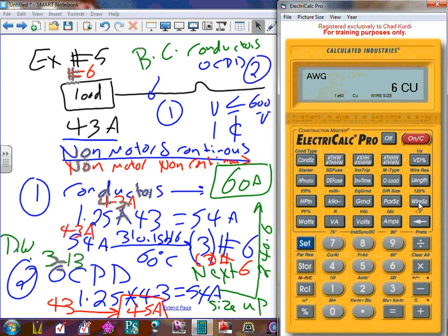I just thought it would be written somewhere. No, it's not written, at least the way I understand it. You can argue that for conductors, if you go to 240.4(B)(3), it tells you you can use the next size up on a conductor, but we're really not talking about that here, we're talking about load. So